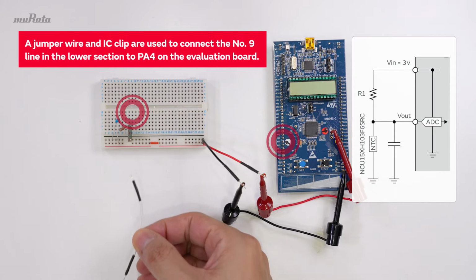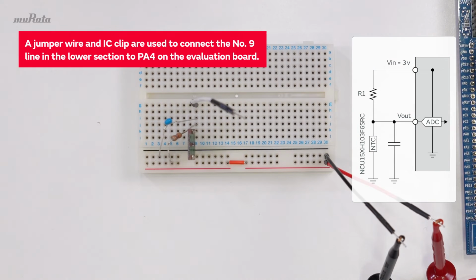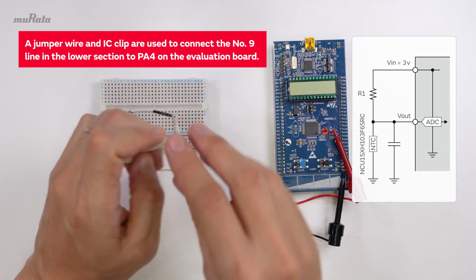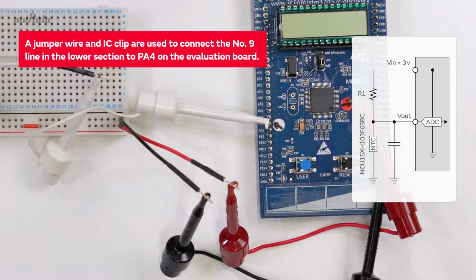Finally, we connect a jumper wire to the number 9 lower section line and secure the other end with an IC clip. We connect the other IC clip to PA4 on the evaluation board. This completes the circuit.